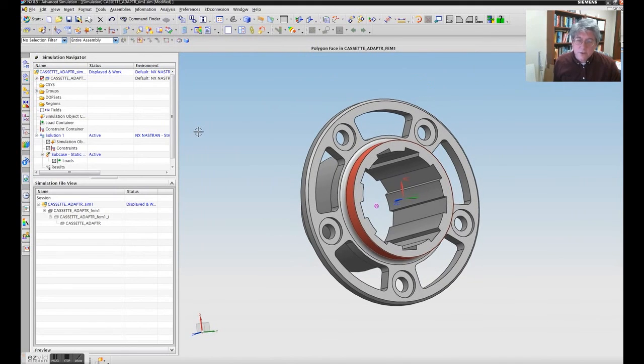So that's really useful. A lot of times you don't want to put the forces or the constraints on the entire face or the entire surface. So that allows you to pick a region, okay? You can draw little sketches to do it or other things, okay? So that one's quite useful as well. Those are the two most common ones I use. You can look through the other ones, all right?